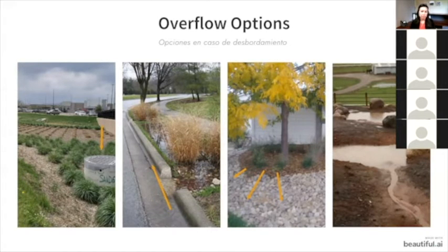This basin will fill up completely, and if it overtops, if it fills up past its capacity, it goes down through the top of this grate here, which is their overflow system. In the second picture from the left, if that rain garden fills up on this street, the water simply continues on the street and passes the rain garden by. If it has the ability to collect more water, water will go into that curb cut, and if it's full, it will pass straight through.